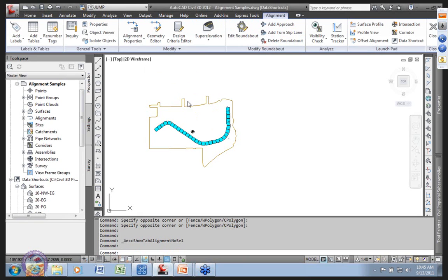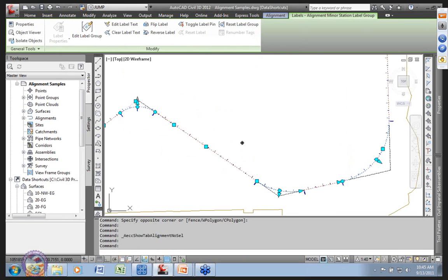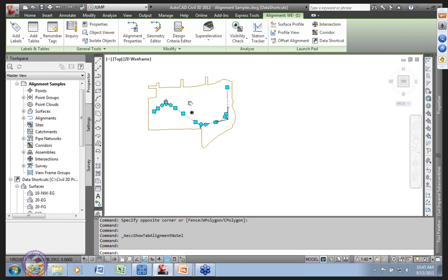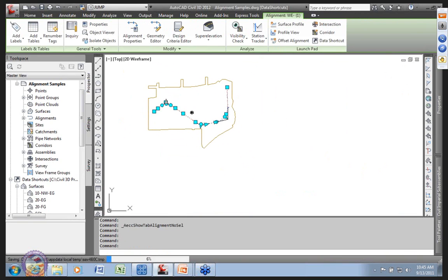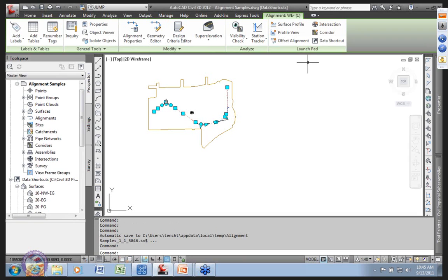Also, when you grab not the labels but the things, based on your interface, there may be some things hidden away in, for example, Launchpad. Classically in 11, if you're still in 11, offset alignments get buried away in the green ribbon for alignments. You may not see them everywhere you want them. So let's do offset alignments.